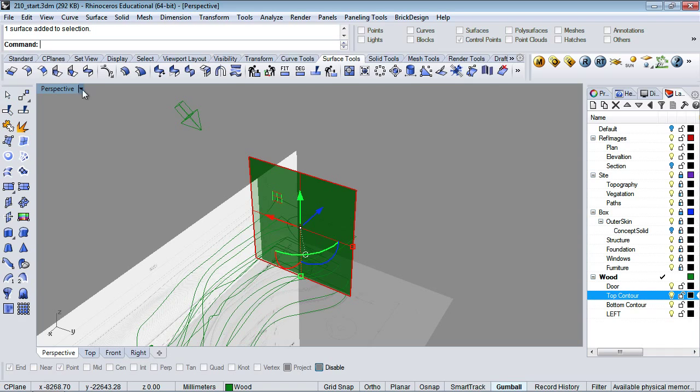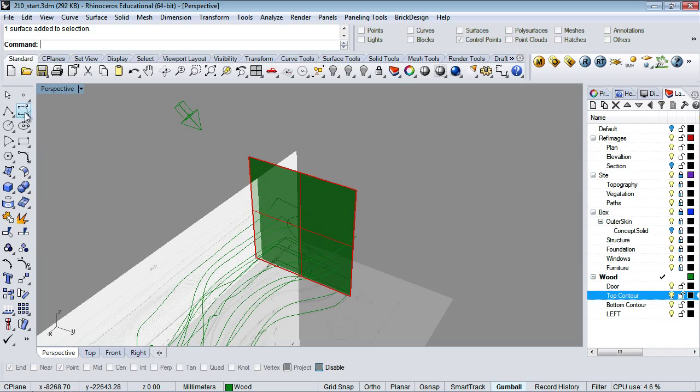And there are tools that you can use. So if we went to standard and we went to control points, if we hold that flyout, we can see that we could draw on this surface. And that could be an option, but what I've found is that when you do that and you're drawing an interpolated curve, sometimes the way it wants to generate that curve starts to be really wonky, because it's actually trying to calculate on the surface. So sometimes you end up with really crazy, hard to control curves. So that's why I prefer to work on the C-plane, creating a construction plane, a C-plane.